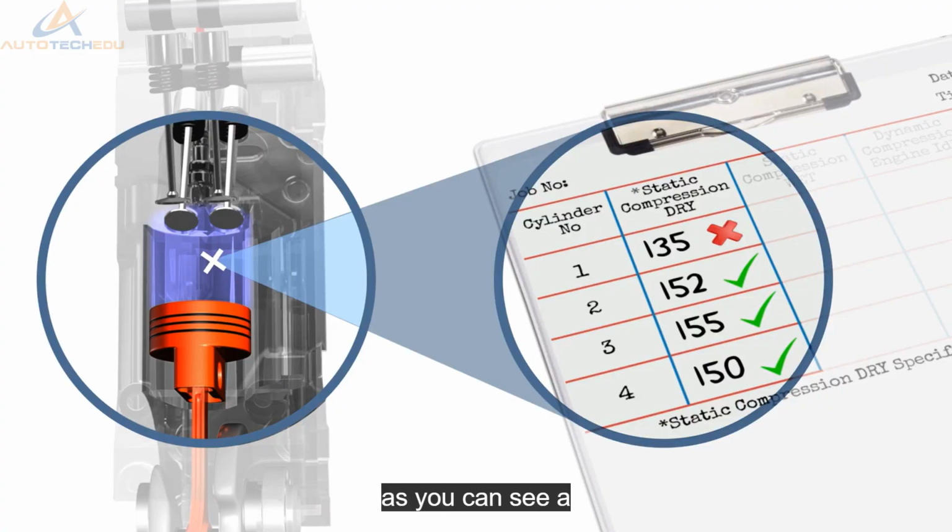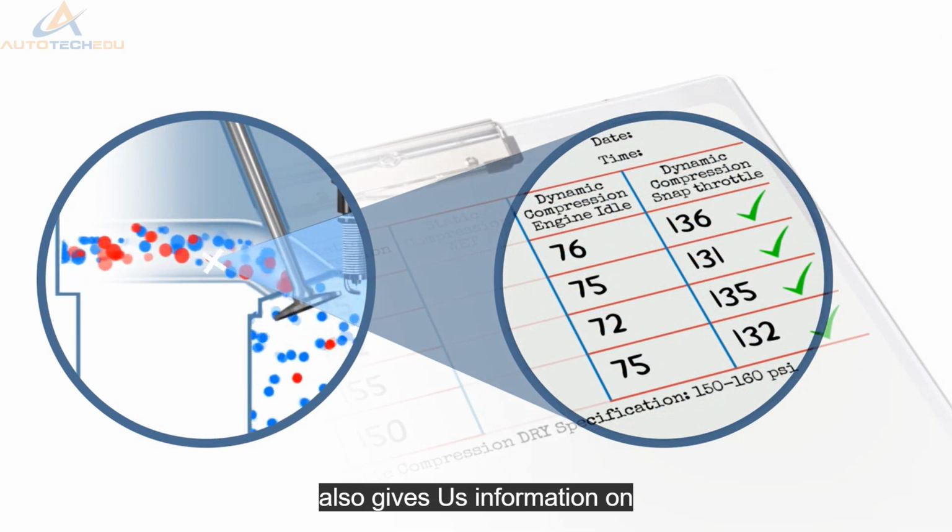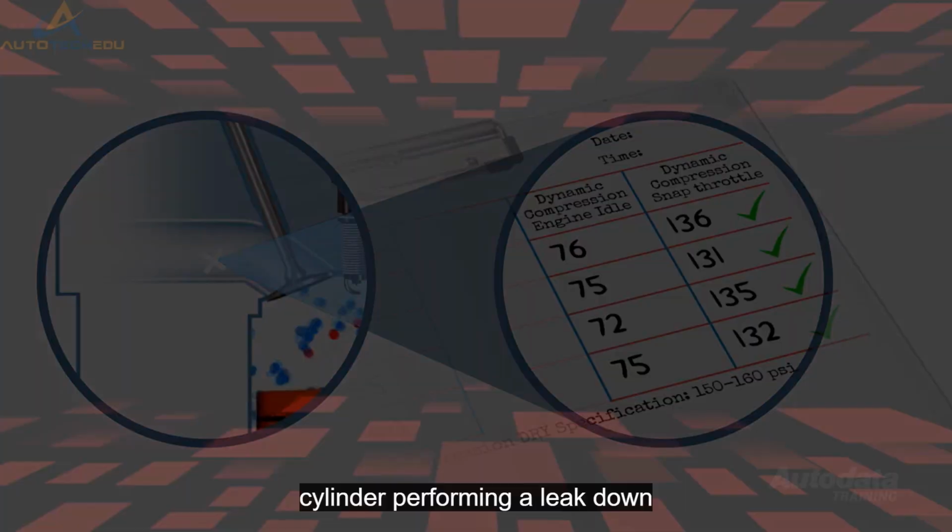As you can see, a static compression test gives us a good indication of what is happening in the combustion chamber, although it will only indicate loss of compression. The dynamic test also gives us information on airflow through the cylinder.